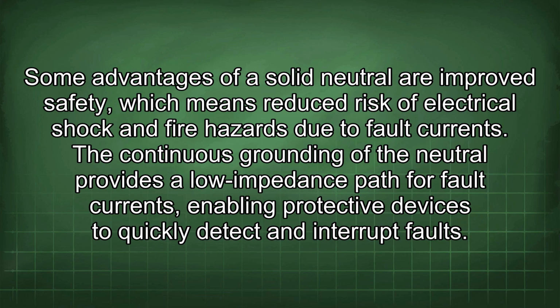Some advantages of a solid neutral are improved safety, which means reduced risk of electrical shock and fire hazards due to fault currents. The continuous grounding of the neutral provides a low impedance path for fault currents, enabling protective devices to quickly detect and interrupt faults.